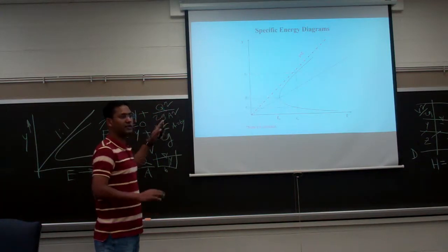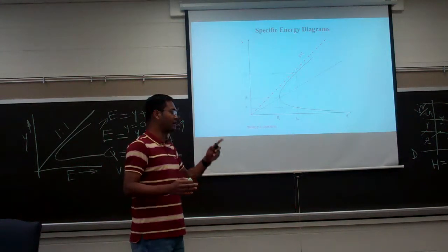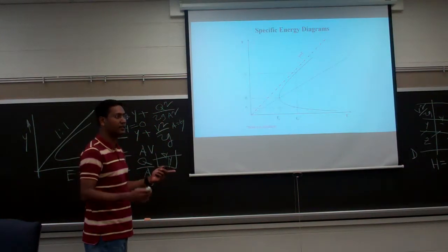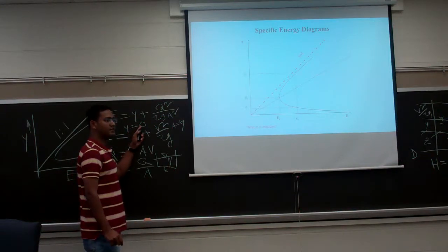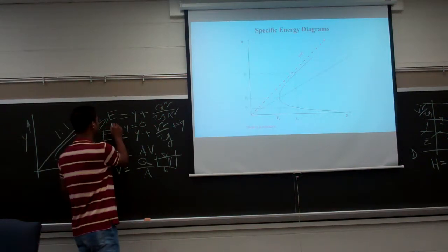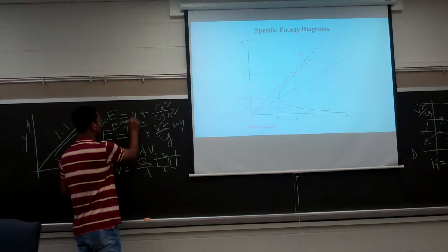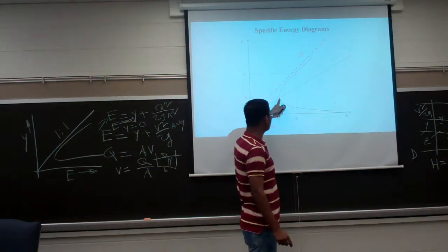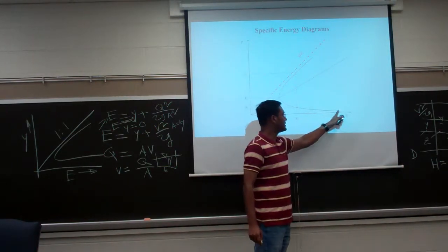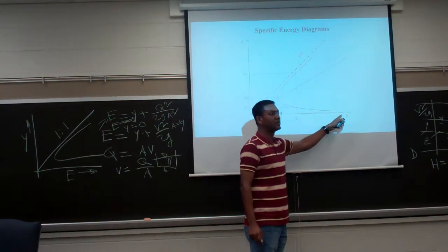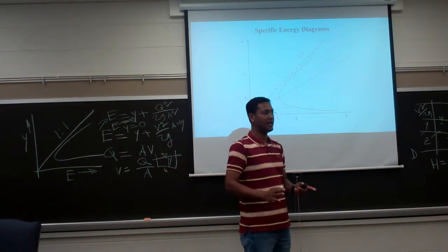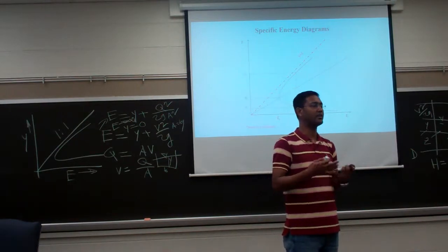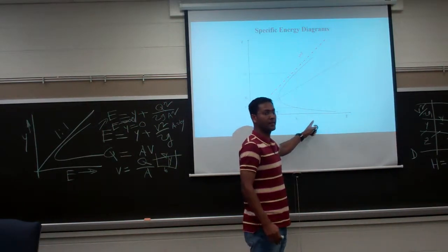And something divided by 0 means it is infinity. And if I add the depth of water to this infinity, the value will also be infinity. That means when the depth of water is 0, the value of E becomes infinity. So from this point, the specific energy curve will approach the horizontal axis asymptotically, but it will never touch this axis, right?